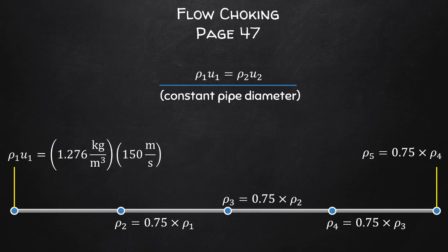Now that we have the two models, we can discuss an important limitation in compressible flows regarding flow choking. Right, so as with any other sort of flow, we have a drop in pressure. Okay, so due to the conservation of mass in a pipe that is of constant volume or a constant diameter, rho times velocity will remain constant.